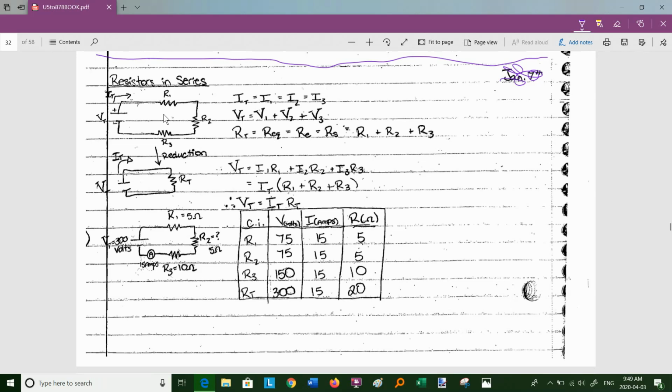They're called cardinal rules actually. There's 3 rules about resistors in series. First is that the current, the total current, T stands for total here, not for temperature, not for period, but for total, is the same. If I put an ammeter near resistor 1, resistor 2, resistor 3, the total current is the same all the way through. The voltage delivered is the sum of the voltage across resistor 1 and resistor 2 and resistor 3. So you add the voltages across 3, you get the total voltage.